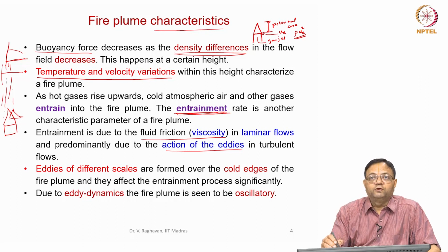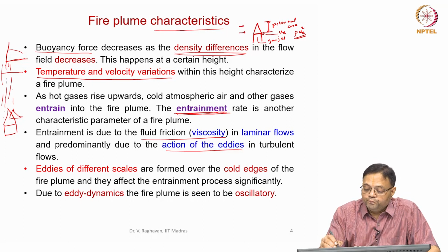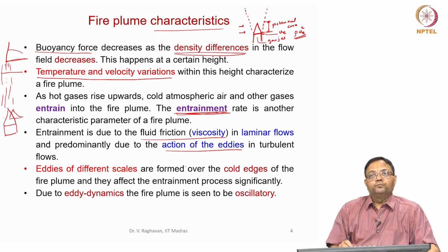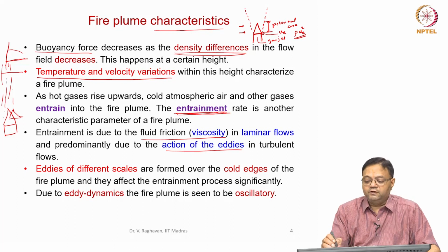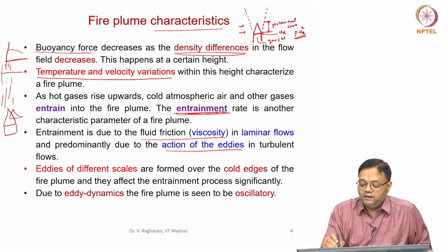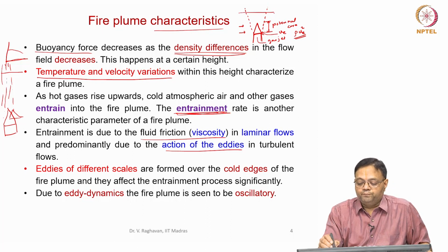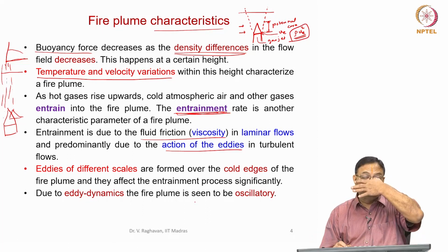Okay, now what happens is, as the gas jet is injected out of this, the atmospheric air entrains into this. So, the jet actually spreads. If this gas is injected in an open environment or without any confinement, then the momentum is conserved. For example, if you take the momentum of the jet at every plane, you will see that the momentum will be the same. Momentum is conserved.